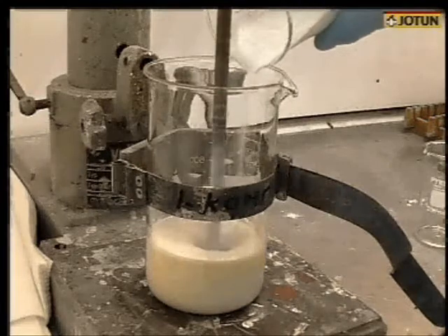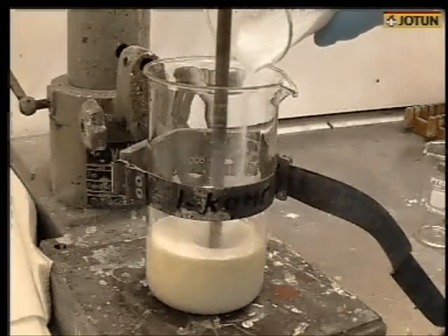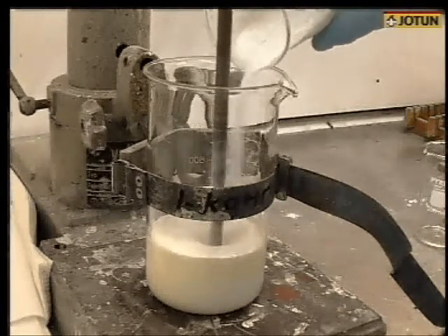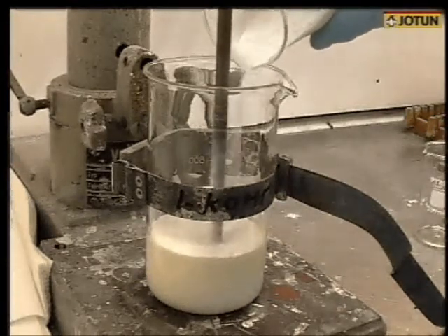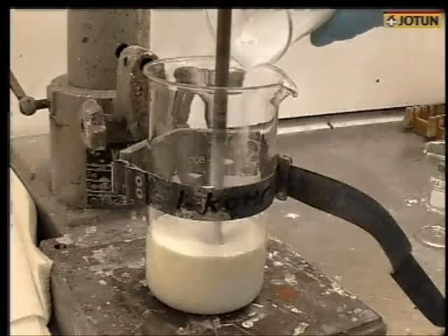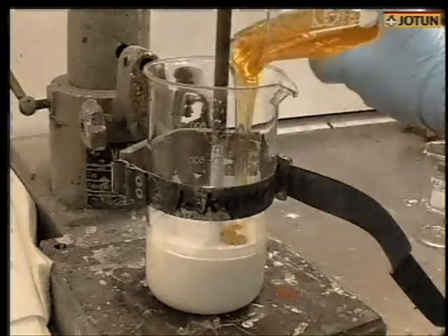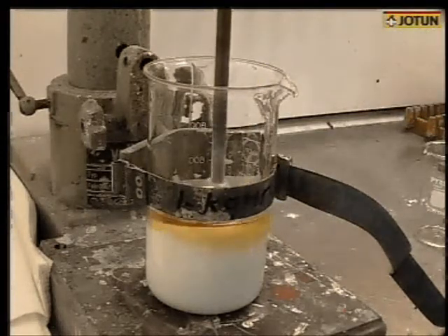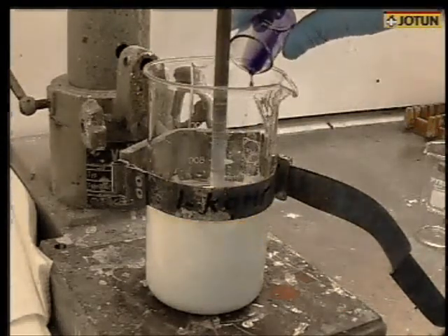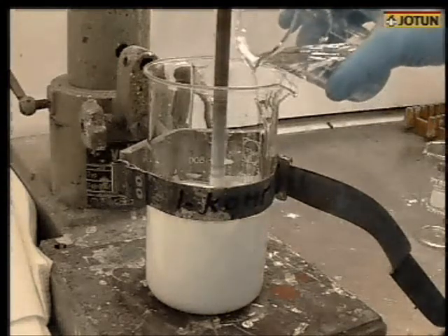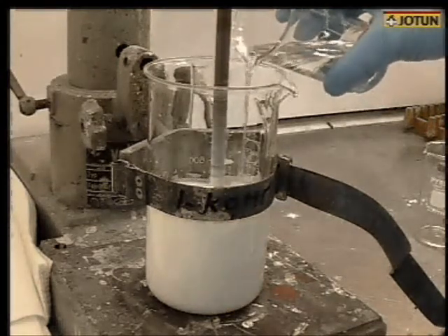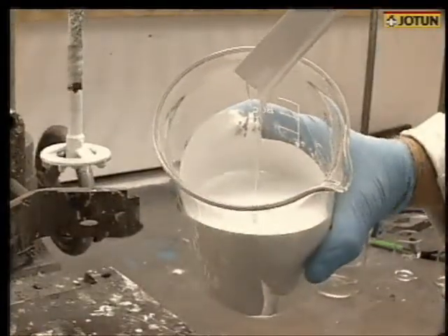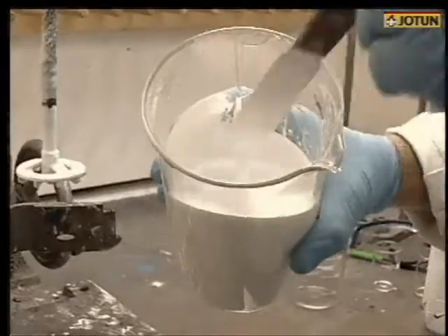The colour pigments will give the paint the desired colour. During production, the solution will be tested to see if the particles are fine enough or whether it's required to disperse for a longer period of time. To this solution, add the rest of the vehicle and additives. Finally, the viscosity is adjusted to the correct level by adding solvents. The paint is then ready to be tinned and shipped to the consumer for application.